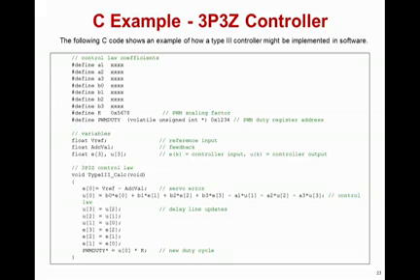This is stored in the input array of E. We then calculate the first element, or element 0, in the output array U. This is done using the equation we saw earlier, and all we do at this point is shift the values in the array such that there is now an empty space at the beginning of both arrays in element 0. At this point, we then output the duty cycle on the PWM and allow the power stage to be controlled using the output of our control law calculation.